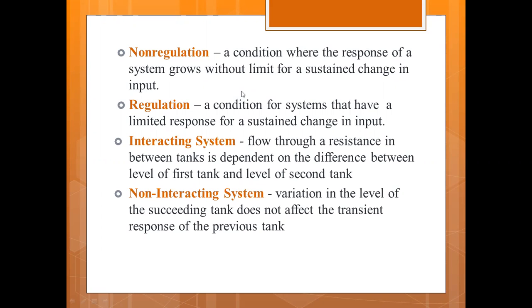Then we have terms like interacting systems and non-interacting systems. Flow through a resistance in between tanks is dependent on the difference between the levels of the first and second tank, so they are said to be interacting. And the irony of the term interacting, if you can still recall it, is that it is using the term that the second tank is loading the first.